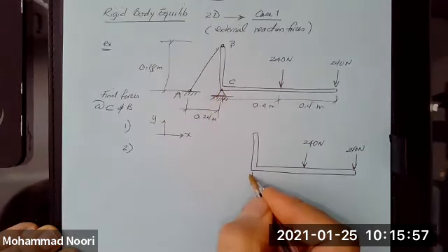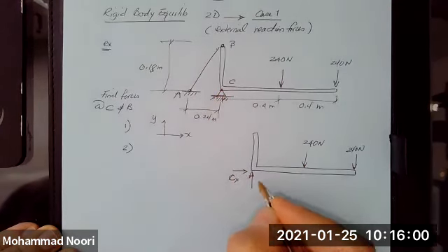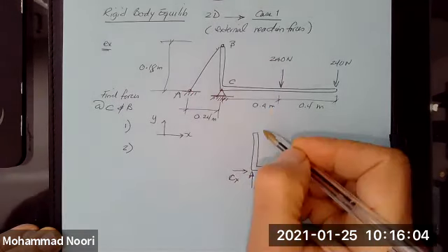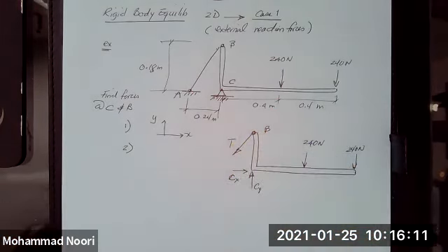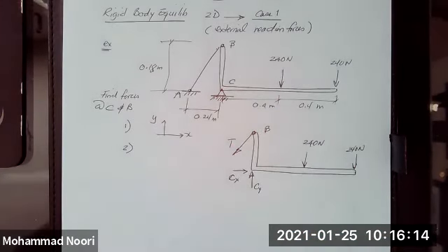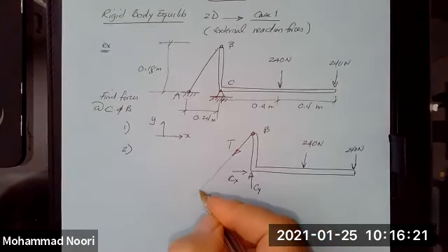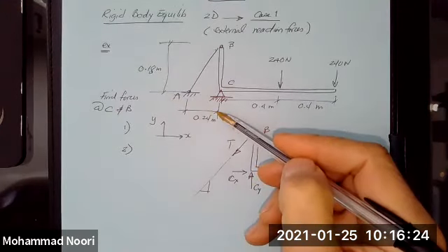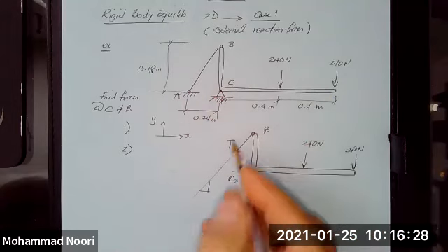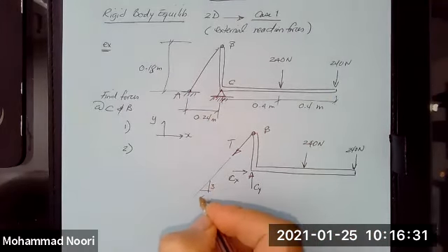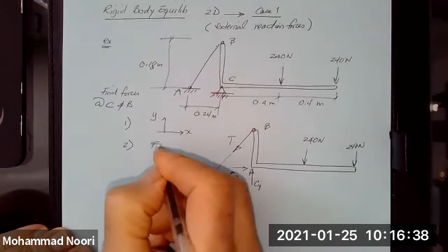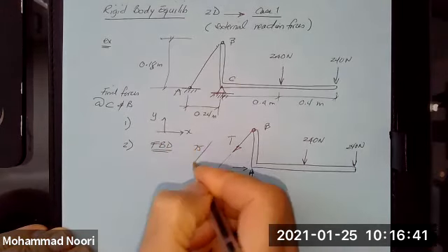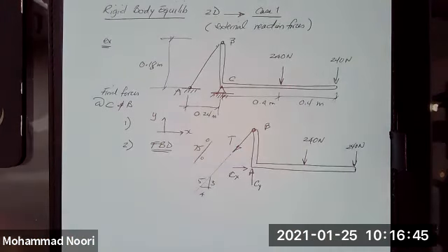At point C, we have a pin. So we have two unknown reaction forces here. At point B, we have a cable attached to the structure. So cable obviously represents one force along the direction that the cable is attached. And by the way, the slope here is given because this is 0.18, 0.24. So if you simplify that, you get this to be a 3, 4, 5 slope. So this is the free body diagram. This is 75% or 80% of the solution process.